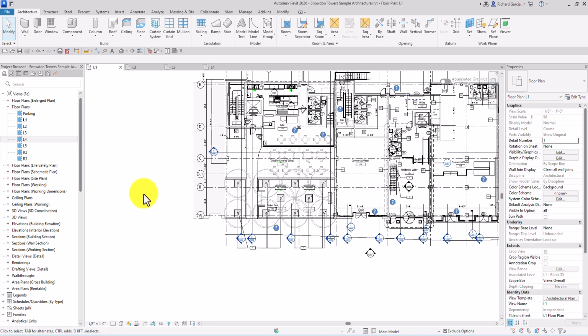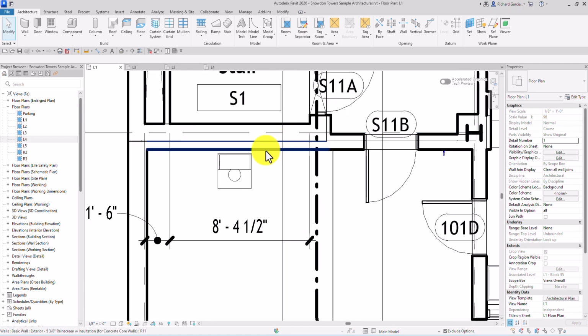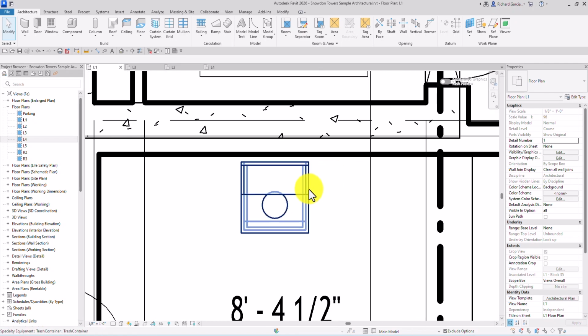It will also tell you what the family is if you hover your pointer. Like for example, this one, you hover your pointer, look at your status bar here, and it tells you that that's specialty equipment. There's also a tooltip appearing on your pointer, but it will disappear eventually.